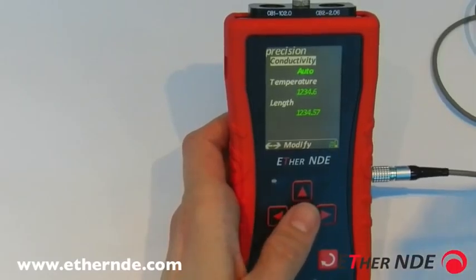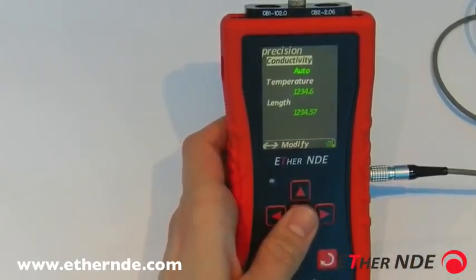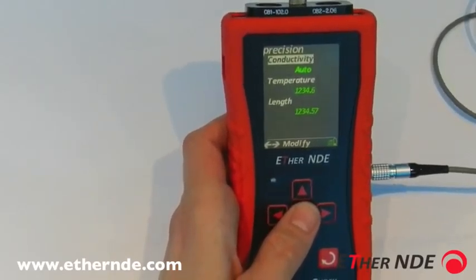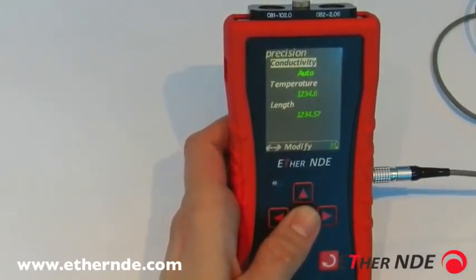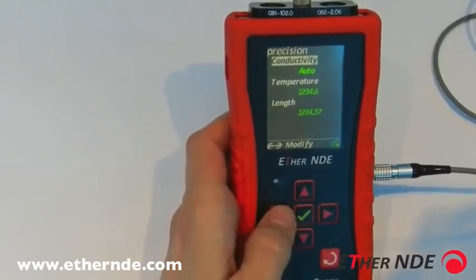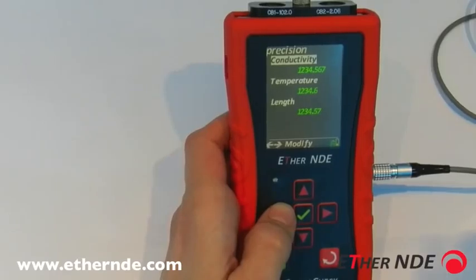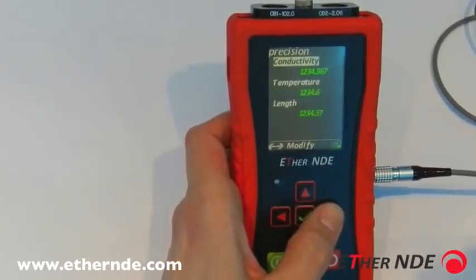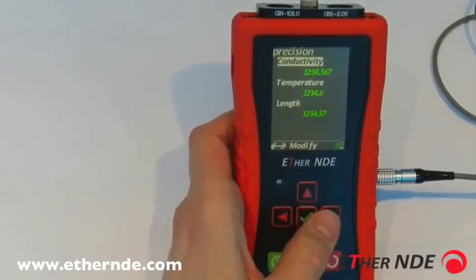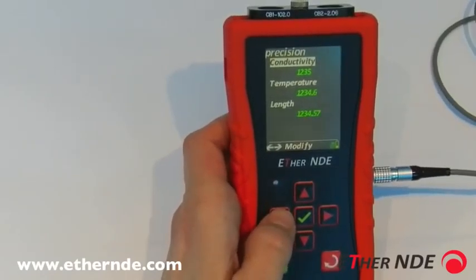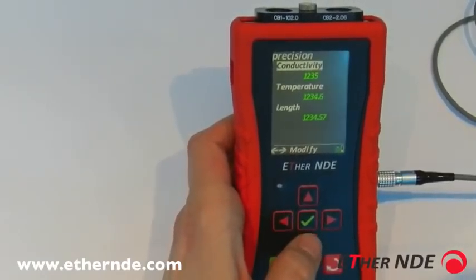For conductivity, we have an auto, where the lower the conductivity, the more decimal points we display, since the instrument is more accurate measuring conductivities at low values. If the user requires a specific number of decimal places, then pressing the left and the right will change the number of decimal points. As you can see, you can go from 3 decimal places, pushing left decreases to 2, to 1, or to 0.